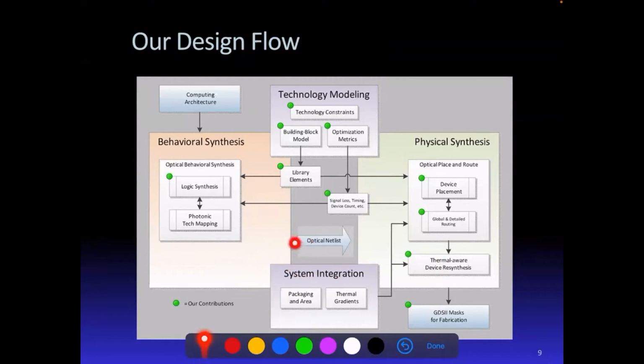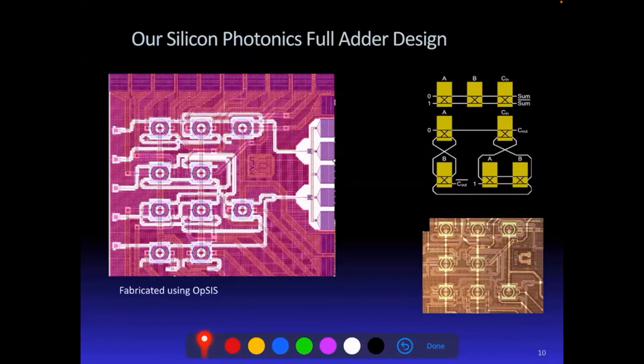Once a chip is designed, before you send it out to the market, you have to test whether there are any problems in the functionality. The problem is that once a chip is available, we only have inputs. In this particular case, we will have lasers coming in and we may have photodetectors, or the other way around. This is where the grating couplers are. This is how you bring light onto the chip. These are switching devices which are built using ring resonators. And here you have some detectors.